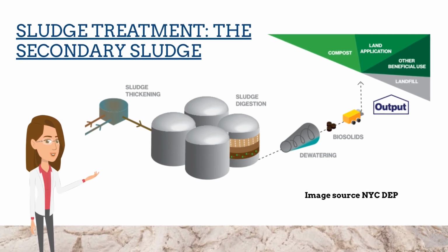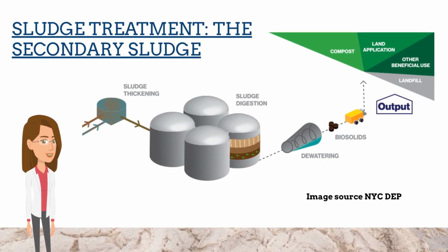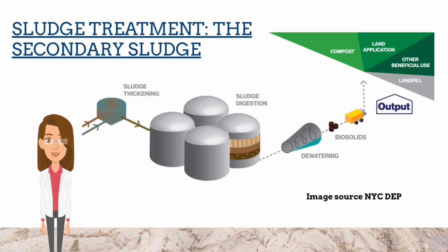The activated sludge collected from the primary and secondary stages as waste is placed into tanks known as digesters. These digesters are set to conditions optimal for microorganisms, low in oxygen and 98 degrees Fahrenheit. These digesters allow microorganisms to process the sludge, converting it into methane gas. The remaining solids are removed of all water and are used in agriculture as fertilizers.